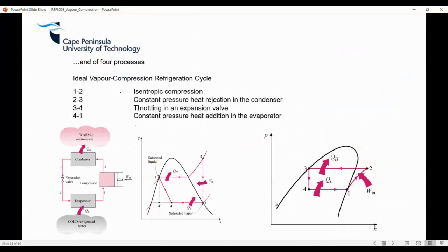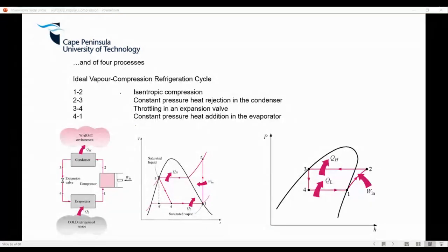Okay, so when we're doing our thermodynamics, we talk cycles. What is the cycle it's employing? For our ideal cycle, we're going to start off with ideal and build up further. From point 1 to 2, our beloved isentropic compression, a straight line. From 2 to 3, we've got this line going up. Point 2 is superheated. If you remember your saturation stuff, maybe I should pull that up quickly, just in case, the saturation line. Obviously, water is still the same.